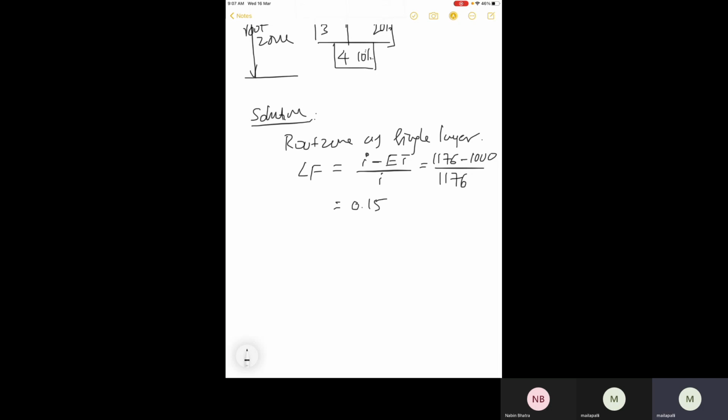Similarly, the electrical conductivity of this drainage water will be ECIW divided by the leachate fraction. So 1 decisiemens per meter divided by the leachate fraction 0.15, and you get 6.7 decisiemens per meter. So what is the meaning of this?